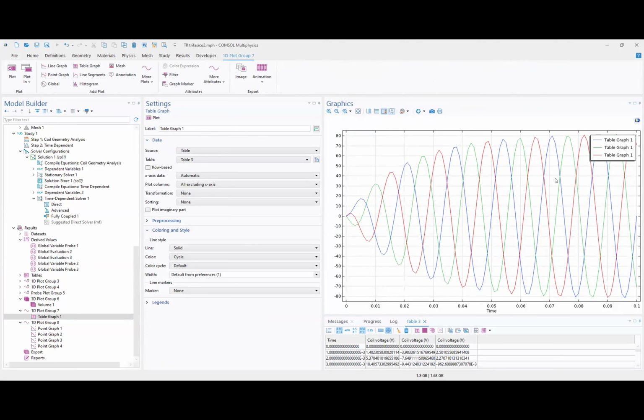You know what I realized? For time-dependent studies, or even stationary, if you reduce the relative tolerance, that avoids the necessity of using a ramping function. I don't use a ramping function anymore. In a time-dependent study, if we control the initial time step, we can make it very small initially. Then the solution gradually increases the driving forces, the excitation.